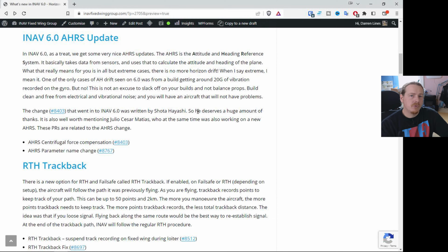So the guy we all really need to thank for this is Shota Hayashi, and he implemented the centrifugal force compensation, which is what really did help get this off. Most occurrences of drift actually happen because of the gravitational pull on the gyro.